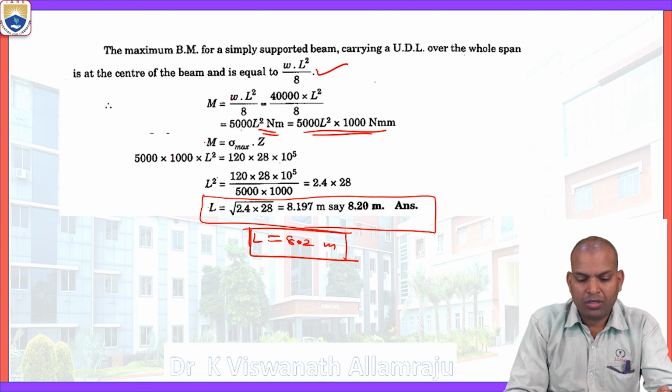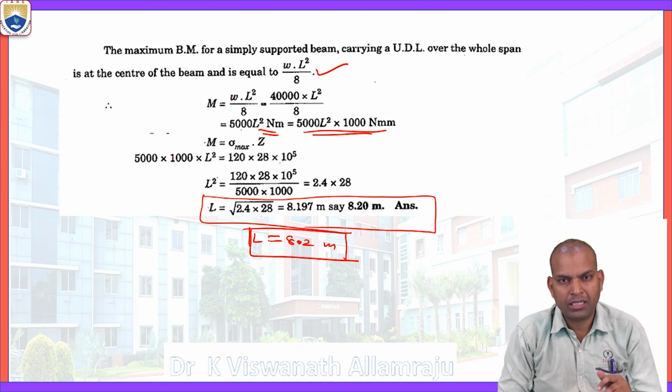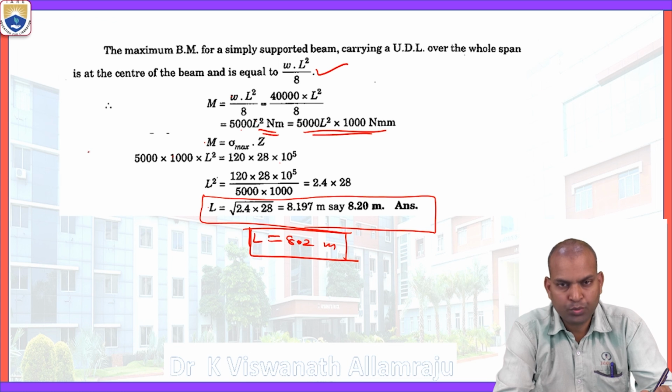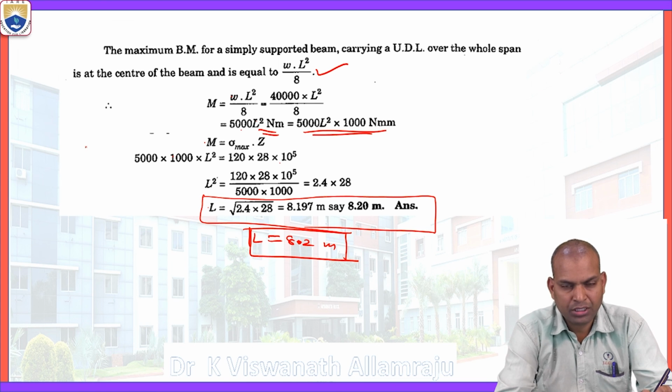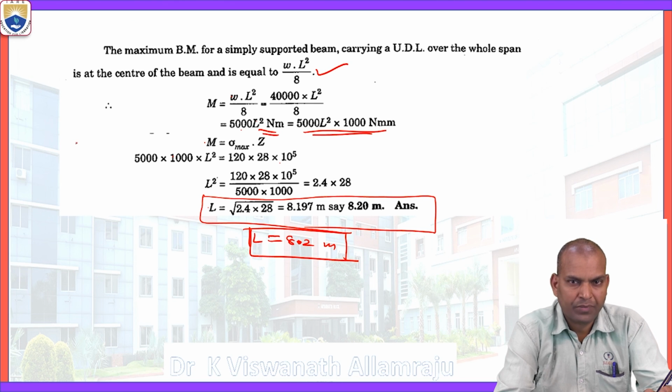One important model also covered here compares 2 beams, a simply supported beam and a cantilever beam, having the same materials but different sections. One cantilever beam is subject to UDL and the simply supported beam to a point load. Because they have the same material, we considered the maximum stress to be the same. Thus we found the value of the uniformly distributed load over the cantilever beam.